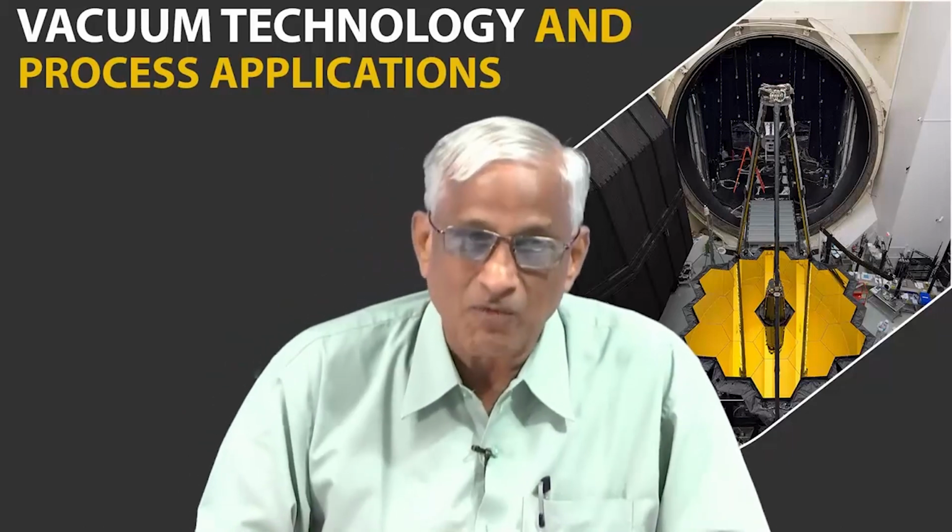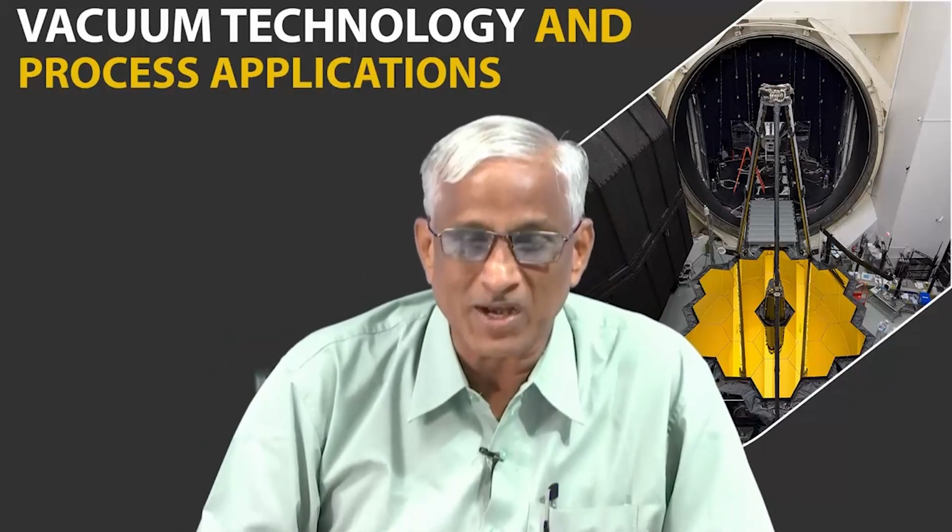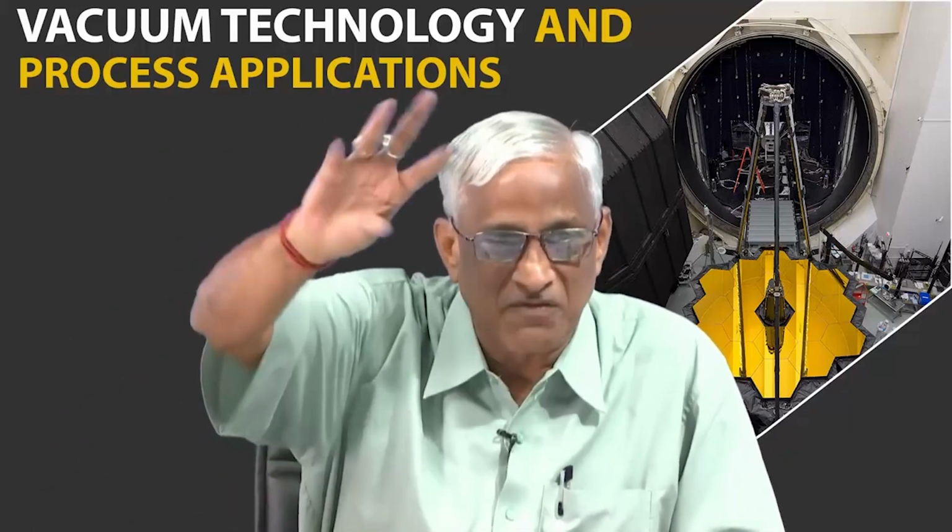So, air blast and tightening, cleaning, all those things are very important. Once it is evacuated to 10 power minus 2 torr, now you switch on the high vacuum by closing the roughing valves and operating the backing lines, and then switching on the high vacuum pumps.